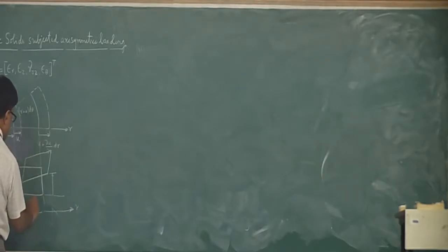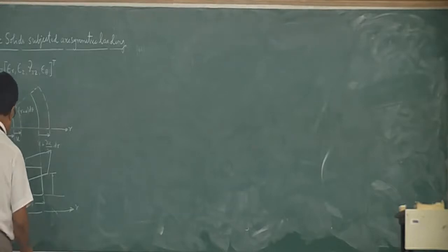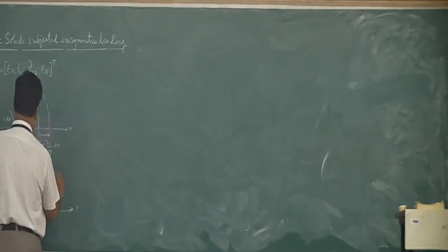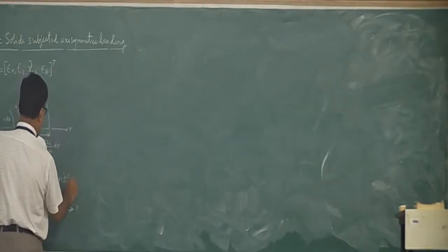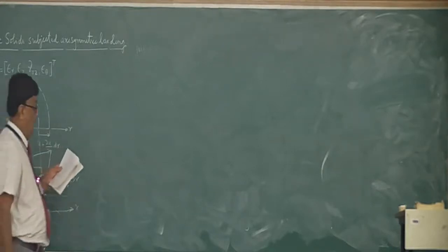The total displacement of this corner from here to here is u. And if you look at the vertical displacement here, it is w. Vertically, this point is correspondingly moving both in r direction and z direction. So this is u and this is w, whereas here it is w plus dou w by dou r into dr. That is going to be the displacement of the other node, like from here it has reached this point. This is the element we are going to take.